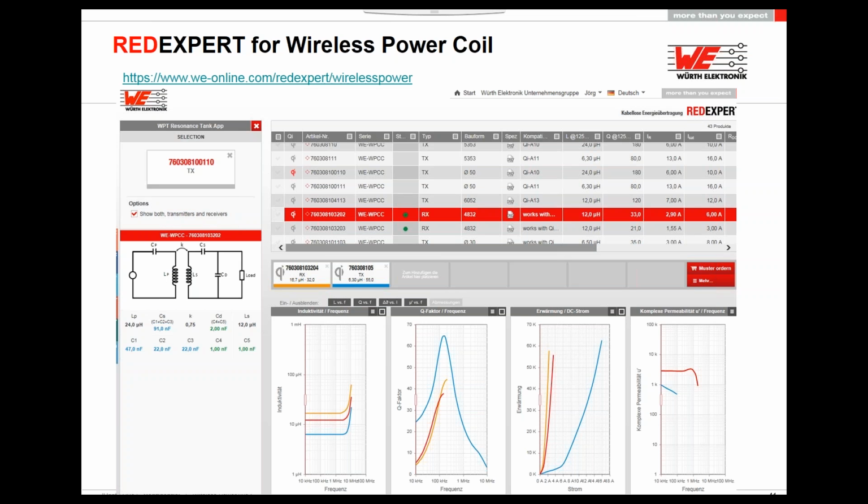The point of that is we did this due to the fact that a lot of customers said, okay, we took the reference design from Texas Instruments or IDT, and it doesn't work properly, the coils get hot, and then we ask normally, have you adopted or adjusted the capacitor values in the resonant tank? And then the customer normally said, oh, have I to do this?